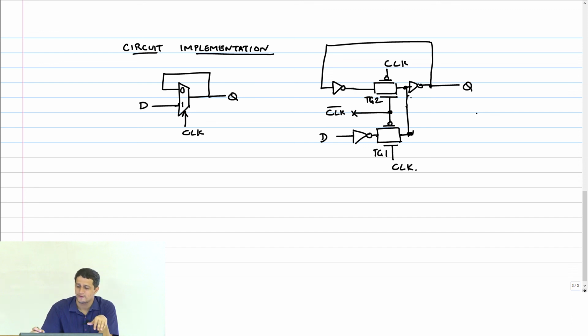Okay, so just be very careful. Sometimes you can get confused if you don't practice this hard enough, where like I did now, you might put the connection here. That can't happen. Remember, the wired-OR connection has to happen at the output of the transmission gate always, nowhere else. Okay.